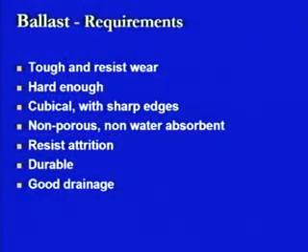So, in all the cases there are certain chances by which the life of this material may get reduced. If they are not durable enough, if they have a mineral composition where certain other minerals coming with the water or other weathering agencies react and they lose strength, then that ballast material is not required. So, the material should be durable enough, it should have adequate resistance against weathering agencies, and that is what durability is. Further, as we have discussed before also, it should have a good drainage property.